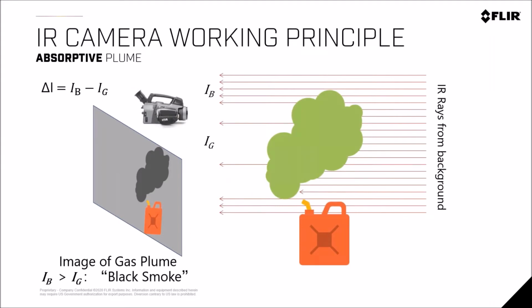There are two different ways. As I showed you a minute ago, when the gas gets between the background and the camera, there are two different scenarios. The majority of the time they use this camera, in particular in the downstream market, you're going to have what we define as a black cloud or an absorptive plume. Again, you can think about it as the background. A minute ago, it was that plant, but the background is sending energy, and this cloud is absorbing the energy and not letting it get to the detector.